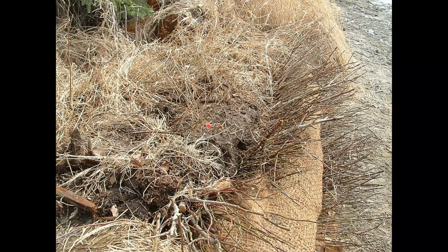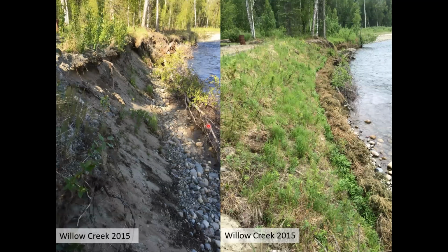Kind of some more examples. So this is Willow Creek. As you can tell, this landowner had a pretty steep bank. Again, there was another workshop class done here, and what they ended up doing was sloping the bank back. And again, as you probably know, a 2-to-1 slope is a lot easier to work with and more stable than a 1-to-1. So the workshop came in, they did a brush layer, and they put some cabled spruce trees in, and then they added a whole bunch of vegetative mat.